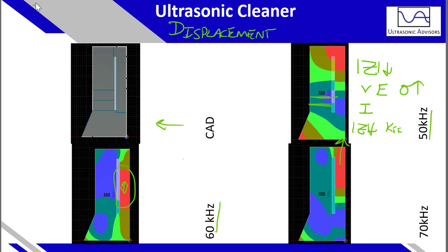Each of the resonant modes, in relation to how the piezo is driving them, will have an appropriate response. The farther away the piezo is from the nodal points, the less coupling and the higher impedance, because the effectiveness of driving will be less. Although you will still see those resonant modes occurring in your impedance analysis.